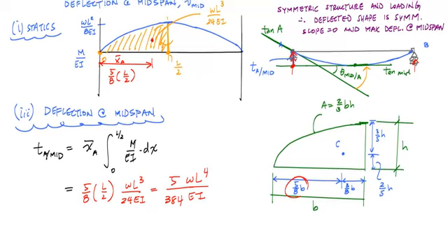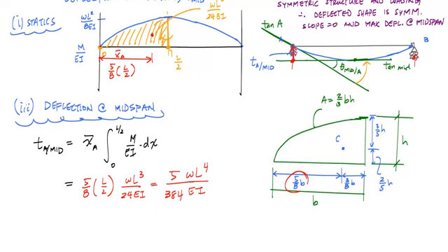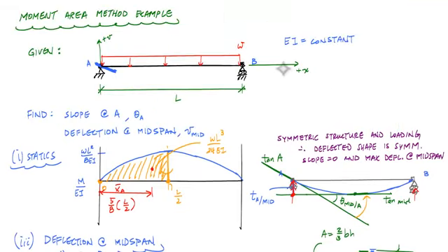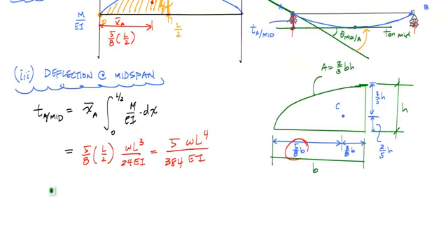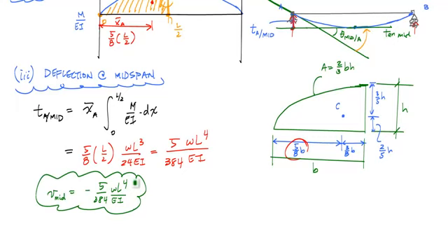But according to our coordinate system for the beam, this V and the X that we established, a point on the beam that's below the x-axis is considered negative. And so in this case, the deflection at midspan is equal to minus 5 over 384 WL to the 4th over EI. Bam! And that's it. That's how to get it done.